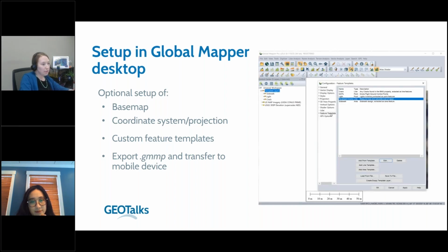Feature templates can be set up in Global Mapper configuration, and this area will probably be empty if you've never made any before. Again, the idea is for you to create them and customize them to whatever particular data is important for you. And you can make as many as you need for whatever different types of features you're collecting.